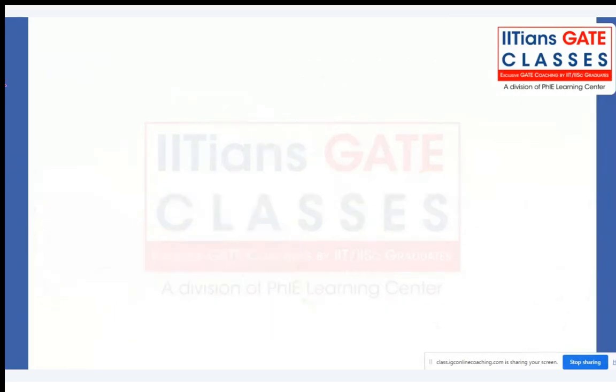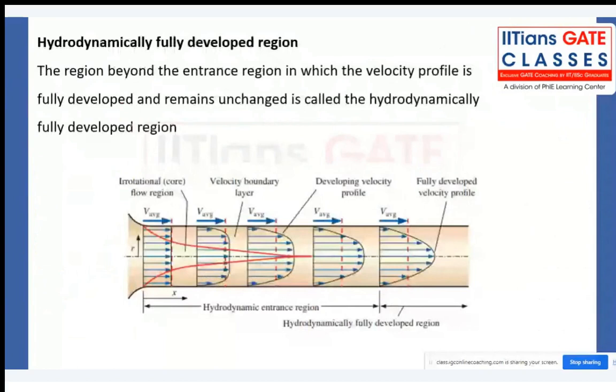Regarding this hydrodynamically fully developed region, we have already discussed that velocity will vary in both directions, in the radial direction as well as in the axial direction, x and r. X in this direction and r in this direction. But when the flow is fully developed, velocity will no longer be a function of x, it will be only a function of r. And this we will prove